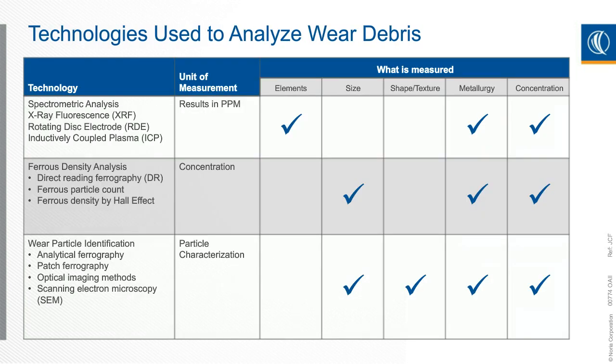So there are several technologies you're going to use to help you analyze the wear debris. Some of those come along with the standard routine analysis that's shown on a typical oil analysis report. Some require a little more in-depth testing being done. Those are called exception tests, and you don't do those routinely.